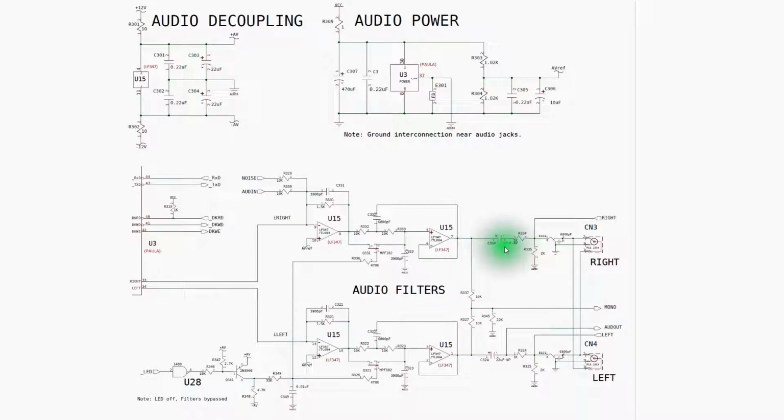And that could put us in a position here where we've essentially got one side of the speaker or the amplifier coming through, and this is, call it 0 volts at that point, and this is swinging negative, and I've now reverse biased this capacitor, and that will over time cause that capacitor to fail. Got the same thing in the left channel here.